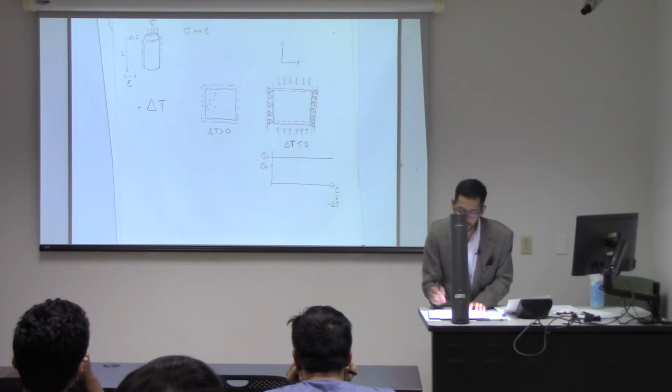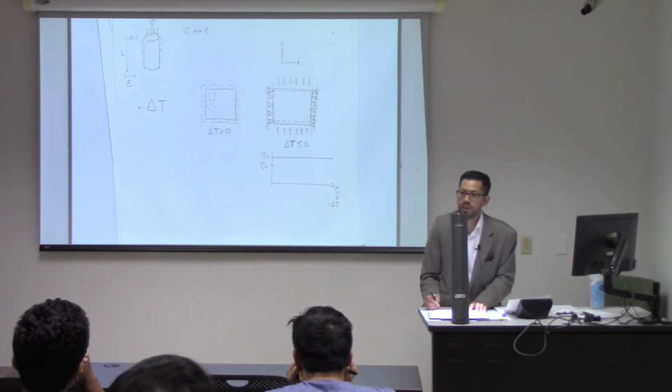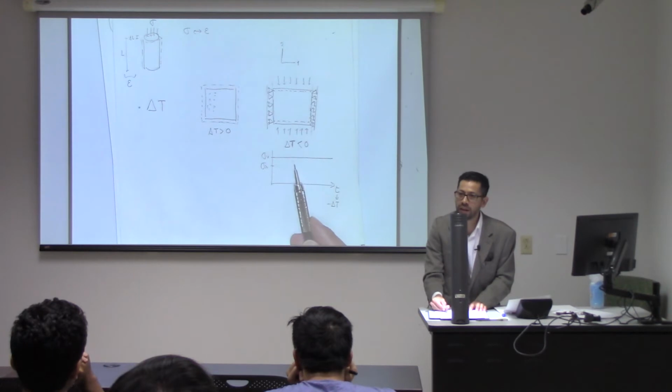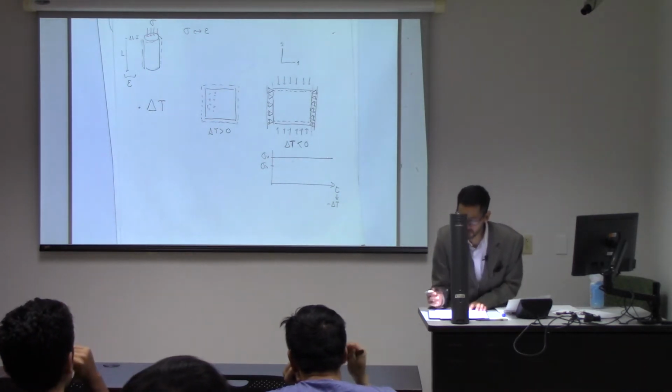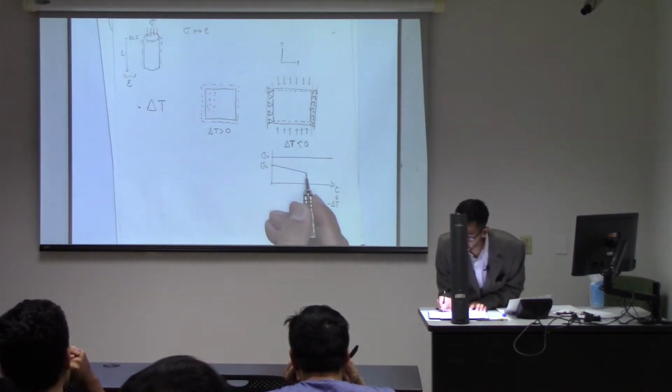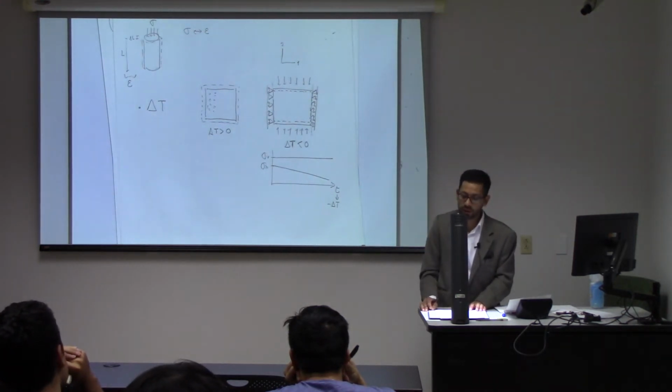So there are three options, okay? This one could, let's say, increase, could stay the same, could decrease. So option number 1, raise your hand if you think that's a solution. Option number 2, no. Option number 3. I see most of the people with option number 3, and actually that's what's going to happen. The horizontal stress is going to decrease.